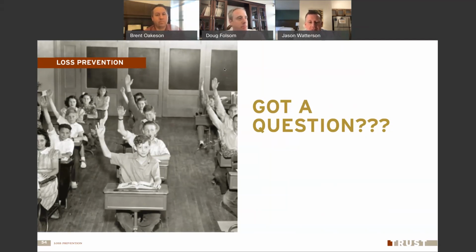One observation that I've had is a little less in the operation of the lift, but more in the surrounding areas and dealing with people. Being able to secure your area. You're up there working along, whatever you're doing, and you drop a hammer. Where's it going to end up? And so just securing those areas. Many times it's not necessarily the fault of the operator that people put themselves in bad places, but at the end of the day, that operator's up in the air, so you've got to be aware and secure that area, and be aware of people in the neighborhood.